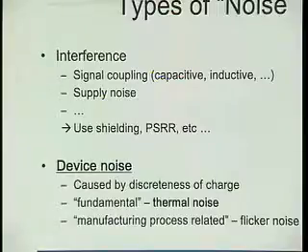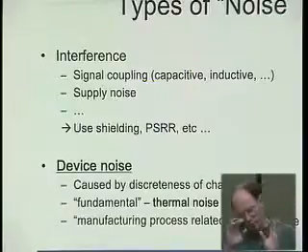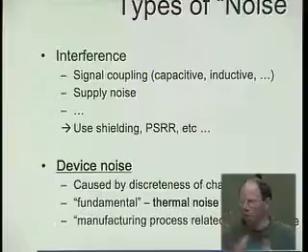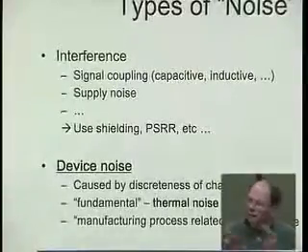Any ideas? Just rough. I mean, it doesn't have to be accurate. Just within 3 orders of magnitude. Okay? Yeah, 30 millivolts? Then you do very, very good if you can do 30 millivolts. Usually, very often actually, you turn on junctions. It's so much. So it's several hundred millivolts often. And of course, you try not to turn on junctions too much because of all the current that flows, right? But typically several hundred millivolts. So really not ground in the SPICE sense.